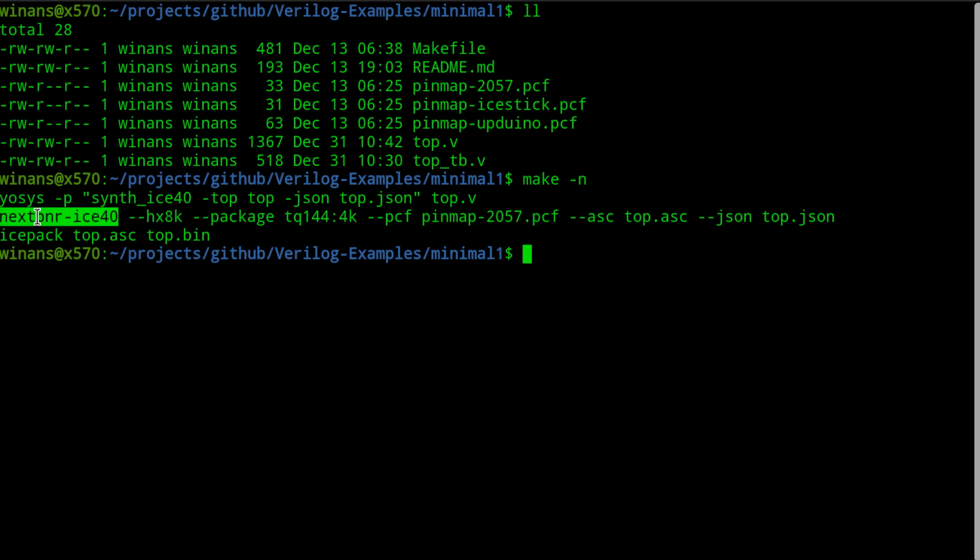And place and route, of course, is the thing that's going to prune off, well, both of them, Yosys and PNR, are both going to prune things off if they're not needed. And a lot of times you'll use a module that somebody else wrote, a general purpose module that might have all kinds of features in there. But you may not use all the features. And what'll happen is it'll figure out that, hey, you're never using some feature X. Therefore, I have a whole lot of LUTs and logic and stuff that doesn't even need to exist, wasting energy and space inside your chip, and it gets optimized away.